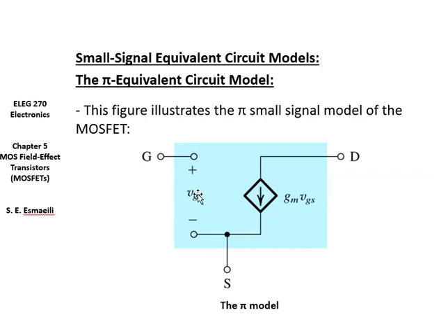Look, again, it's very similar to what we were doing in the BJT with one difference. Over there, you used to have a resistor here. You used to call it R pi, between the base and the emitter. Here, you have nothing. It's like an open circuit with the voltage of VGS.